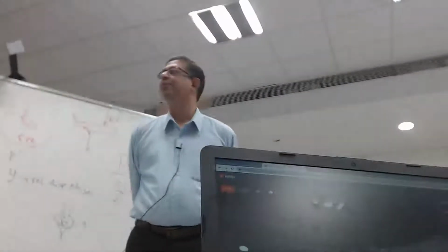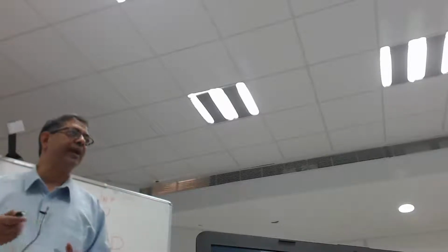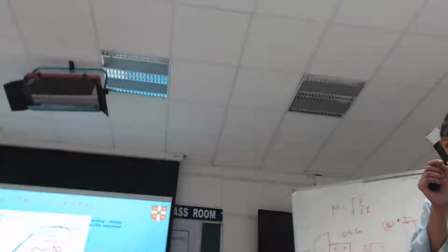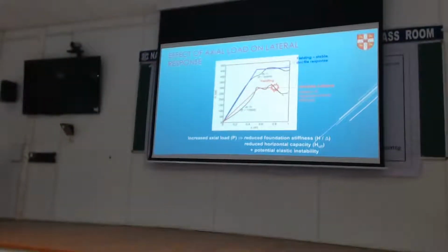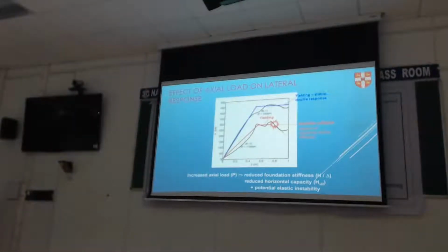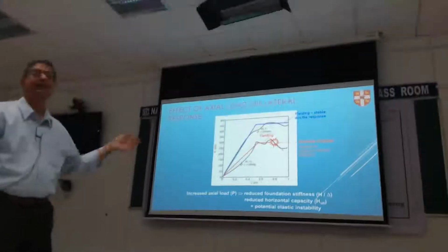And the more you put on in terms of axial load, it can do less in terms of the horizontal resistance. You can't have it both because the material can only do so much. So that's a simpler way of explaining it, but this is quantitative. You can actually work this out. You can plot these graphs and see where you fall, and then work out exactly what capacity you got. So from a design point of view, you really need charts like this.